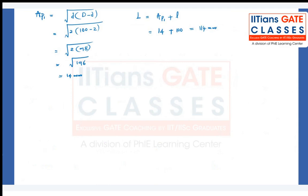Now, from the given data, your cutting speed V is equal to pi d n by 1000. Here it is given 20 is equal to pi into d, which is 100, into n, divided by 1000.